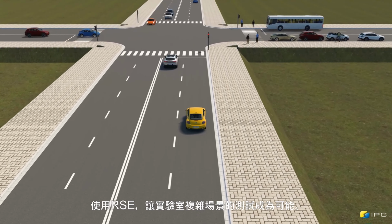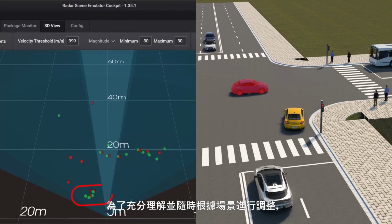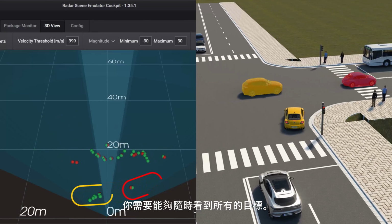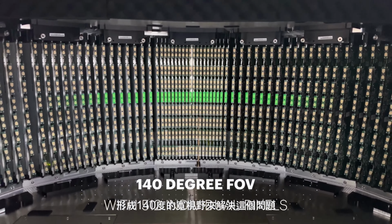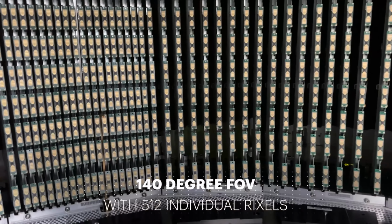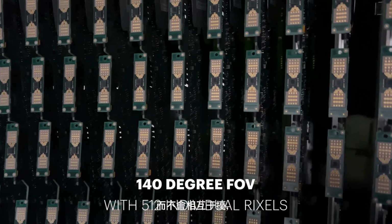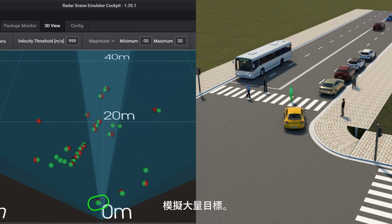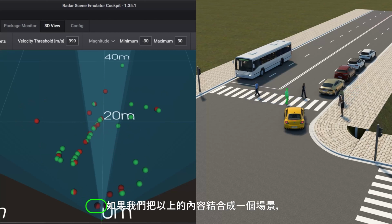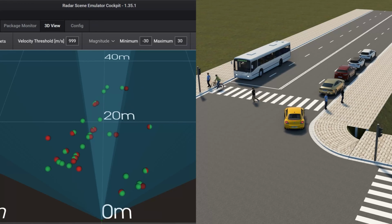With the RSE, this type of test setup is possible. To fully understand and adjust for the scene, you need to be able to see all the objects all the time. The RSE addresses this by employing a very wide 140-degree field of view that holds 64 rixels in one row. The rixels are individually controlled and can all be simultaneously switched on without interference between them, enabling you to depict a large number of objects from a broad field of view. If we combine the above into one scenario, we get a complex urban scene with pedestrians and cross-traffic.